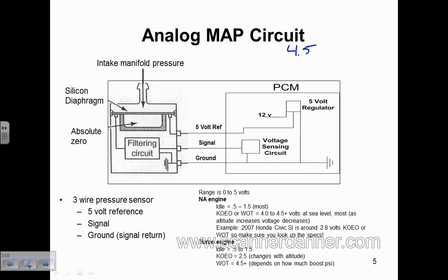Okay? So you have a car with a MAP sensor trouble code, and you start the car and it stays at high voltage. It's an indication of a problem on that circuit. And you pick that up from the driver's seat, sitting there looking at the scan tool, because you know fundamentals. What should this thing do? How should it react? We want to see this thing drop, and then with the engine idling, generally between 1 and 1.5 volts. So these are some ballpark numbers I'm writing down for you guys.